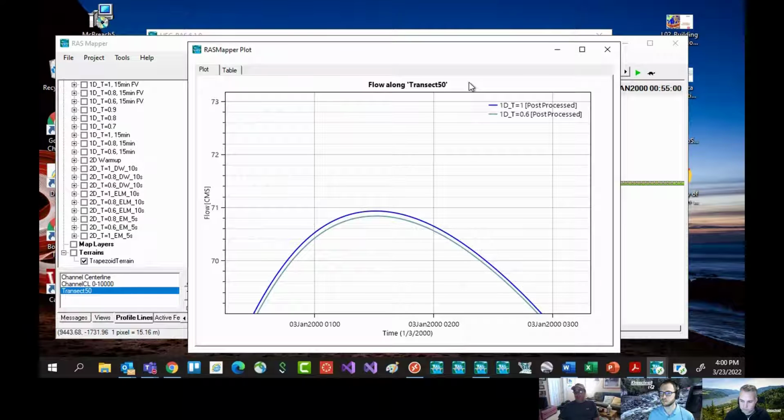Well, you sure as heck should run a run with 250-foot spacing and an appropriate time step to go along with it for a Courant number based on that smaller spacing, and then compare that to your 500-foot larger time step run. And if there's a significant difference, that tells you, okay, your 500-foot wasn't good enough. And then you don't know if your 250 foot's good enough unless you cut that in half, maybe again, okay, and go down to 125 foot.